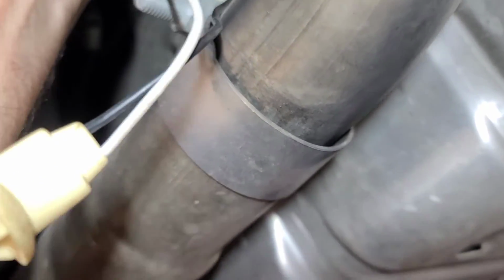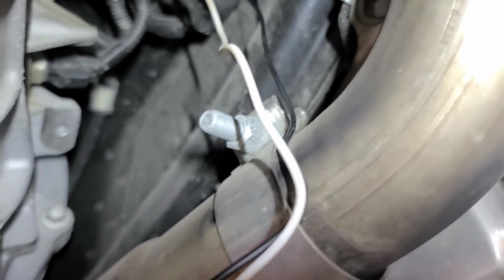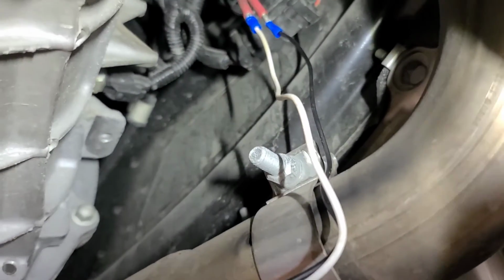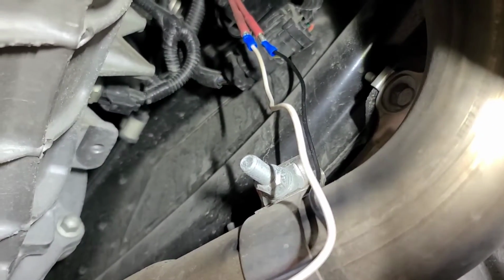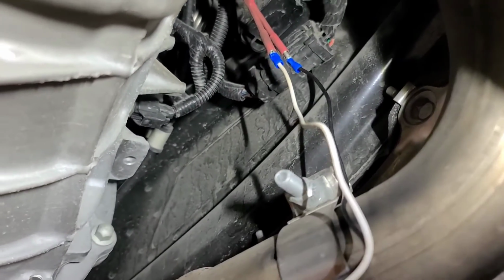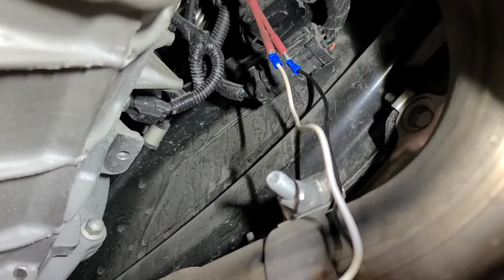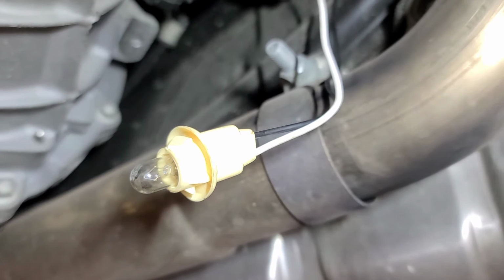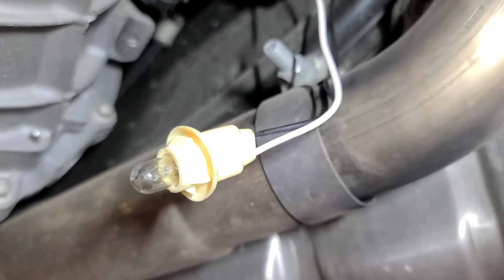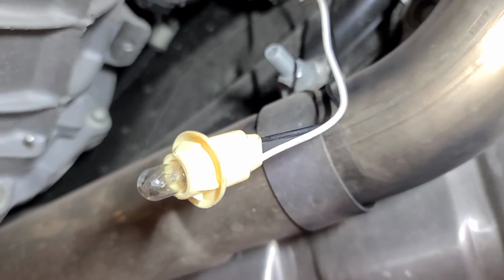Usually if they fail, it's right at the harness here because of vibration, right where the pigtail comes out. But technically now we've got to look to see if there's a connector between here and the ECM, wherever that lives. I think it's behind the left front tire. But there's an open in the control, or that function is not working on the scan tool. Maybe I'll try a couple different things.